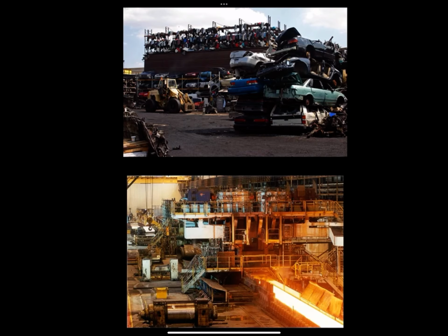Steel does not have any thermal mass. On the plus side of the equation, steel can have a much lower embodied energy, particularly the steel that we use for buildings. Most of it is recycled. Two-thirds of all the steel made for building construction comes from recycled metal. And steel can be recycled multiple times without losing any of its structural qualities.